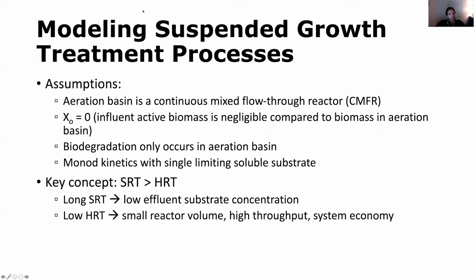So the long SRT makes for conditions that produce a low effluent substrate concentration because you've got very efficient biodegradation taking place, leading to a low COD or BOD concentration in the effluent. The low hydraulic retention time leads to us being able to design a smaller reactor volume, which saves on costs, saves on land space. It's a high throughput system with an economy of scale for treating wastewater.